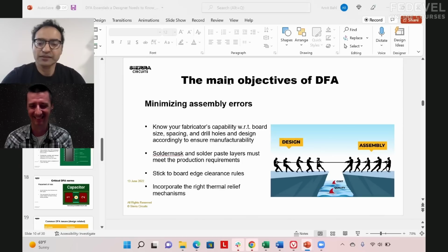So I'll give you an example. If you designed your board and then the component's not available and you have to pick a different footprint for the same component, or the fabricator suggested an alternative component which has a different footprint, there are things that will induce the mistake that may not even be the designer's issue. Right now things change all the time. But you're right, it should not happen.